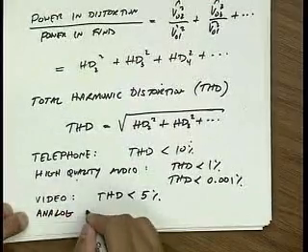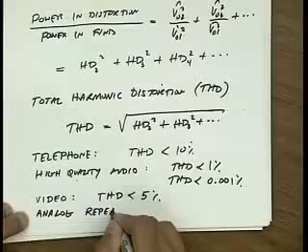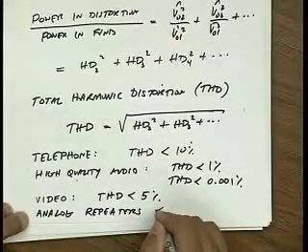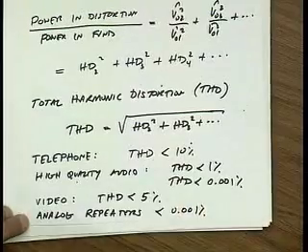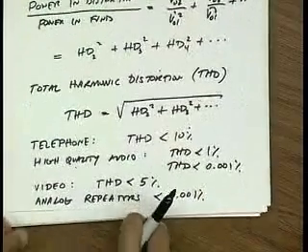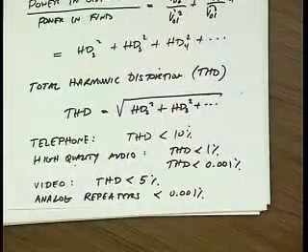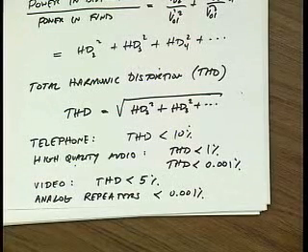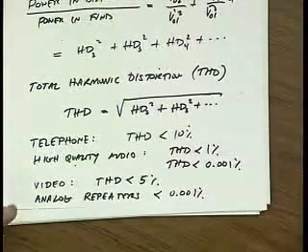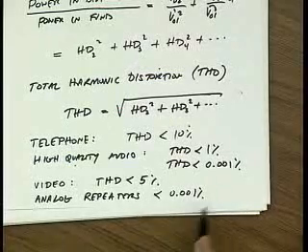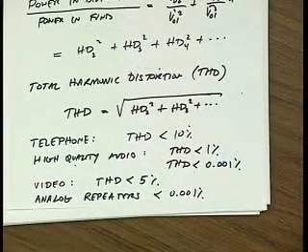If you're looking at, let's say, analog repeaters, they need to be very good. You're not stupid for buying a repeater that has this little distortion, because if you think about sending video from, let's say, your cable operator down to millions of homes and having repeater amplifiers all along, we'll see that if the distortion levels aren't very well controlled, all the channels would get mixed up.